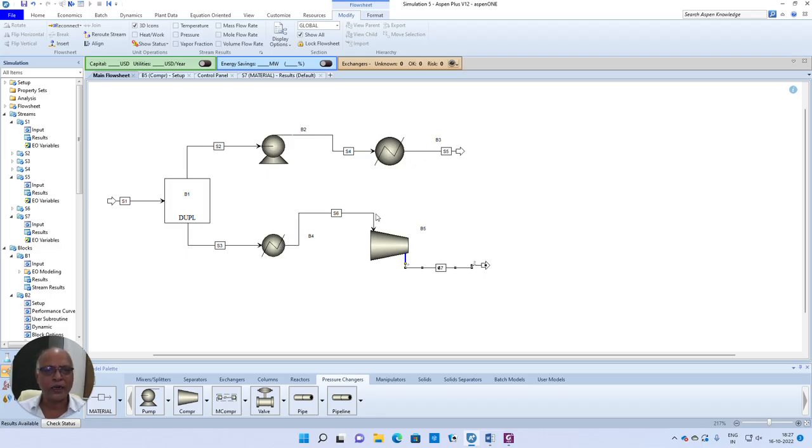So 500 inlet available at 14.7 psia, when it is compressed to 73.48, the temperature was increasing from 500 to about 583. Now we should be able to finalize this temperature such that when it is compressed from 14.7 to the exit pressure of 73.48, we must be in a position to get the required outlet temperature of 752.